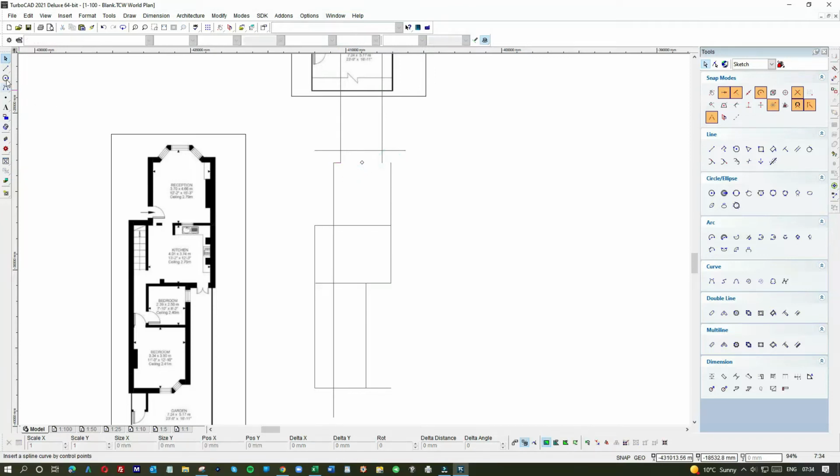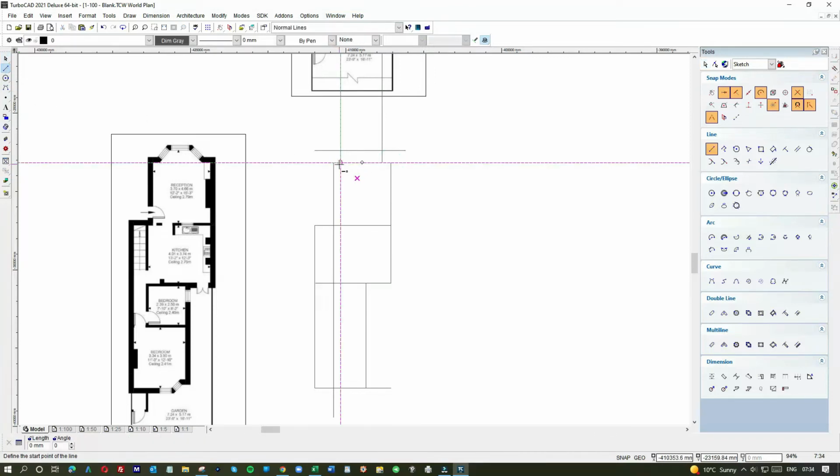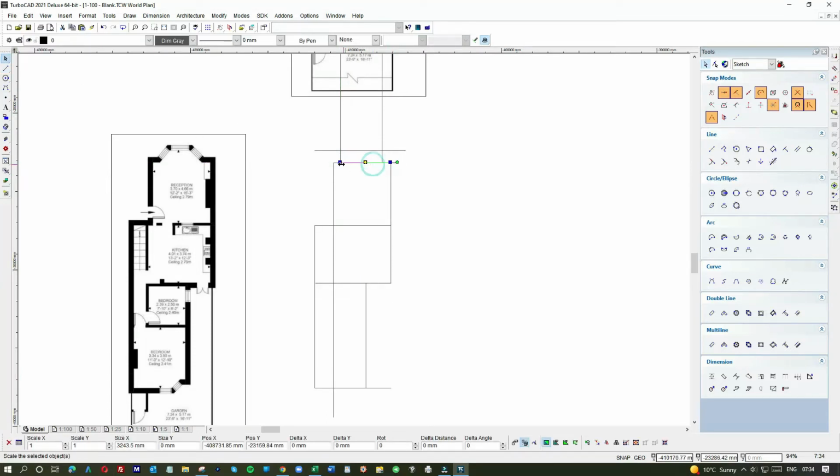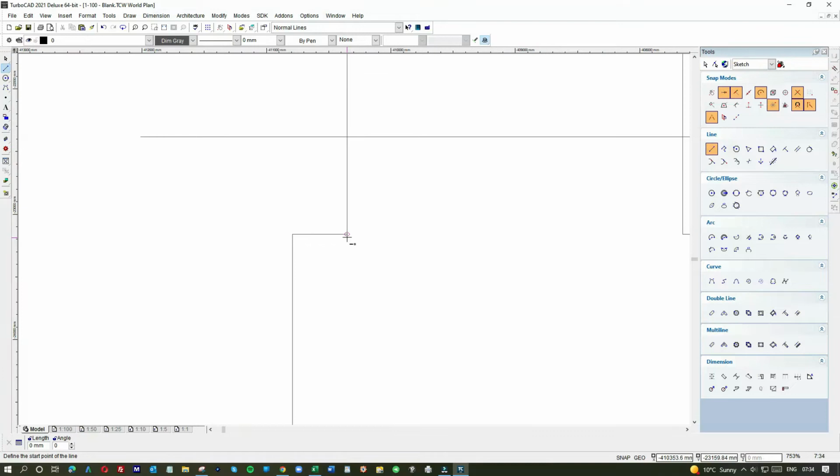So most bays, when we're drawing them, we tend to do them at 45. And may not be strictly accurate, but it's close enough to give us what we need. So here, I'm going to draw at 45. So you can click the auto, or you can just press shift and then tab down. So let's get to the angle. The angle should be 45.